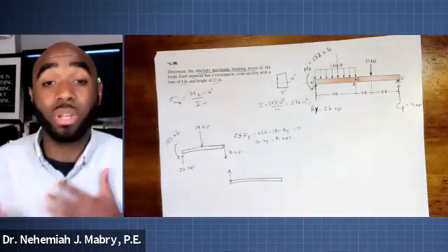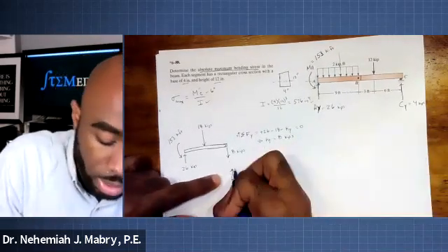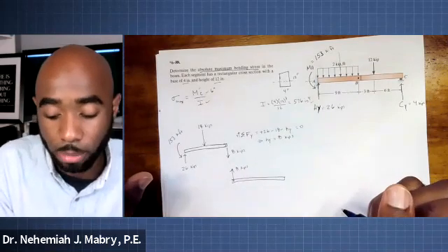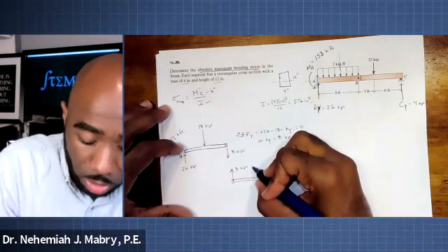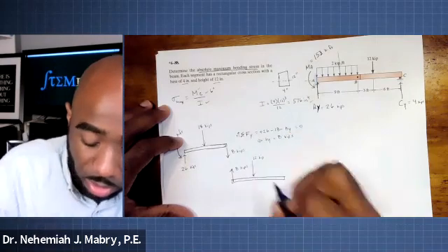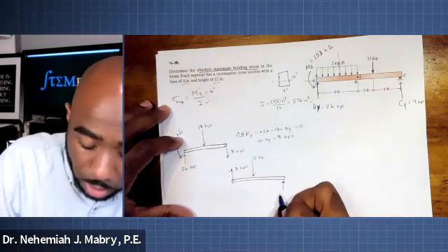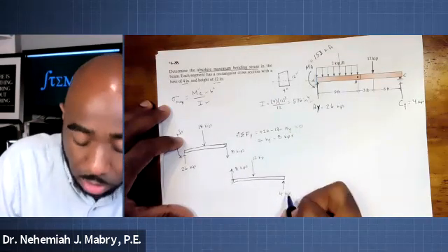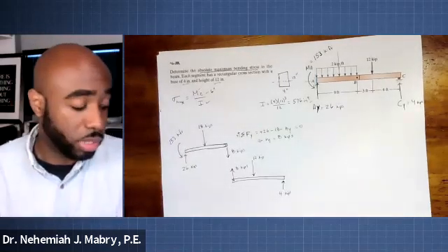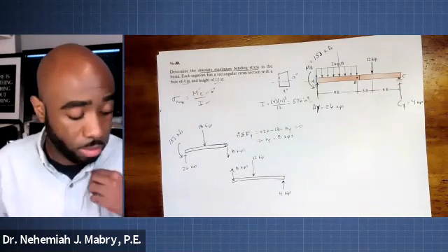And because this is an equilibrium, that automatically gives us a head start that this second portion also has 8 kips. Let me finish drawing the forces here. We know 3 feet over, this here is a 12 kip force. And then over here, we have a vertical force, Cy, of 4 kips. So that's what the hinge is. Just know that there's going to be a counteracting vertical force. Internally, we know the value is 8 kips, 8 kips.